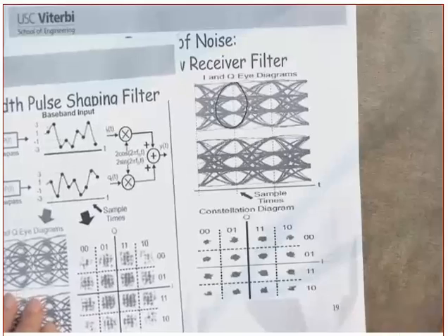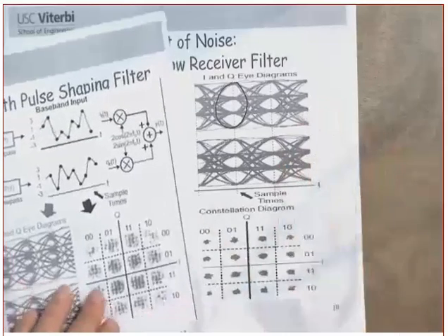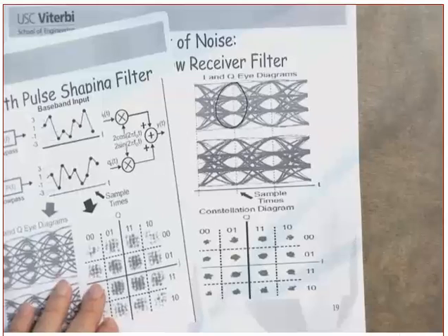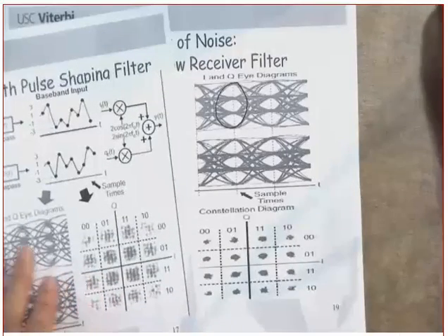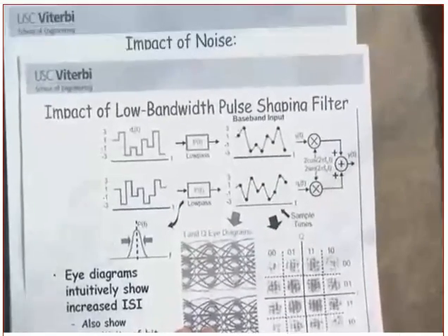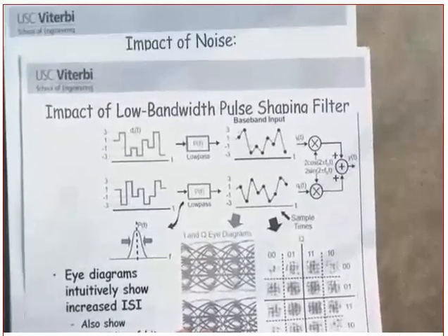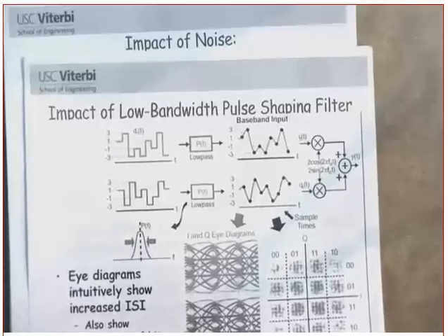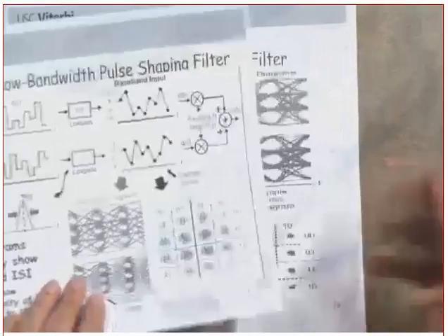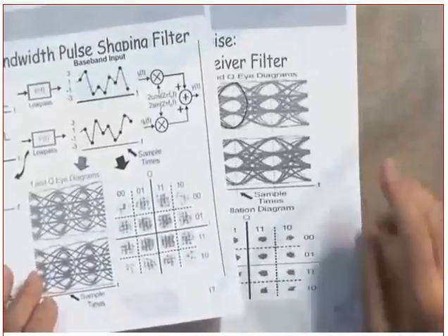The I has 2 bits and the Q has what? 2 bits. Yes. The 2 bits represent what? For the I, the 2 bits represent 4 levels, which is plus or minus 1, plus or minus 3, separately on the I and the Q. Okay, continue.